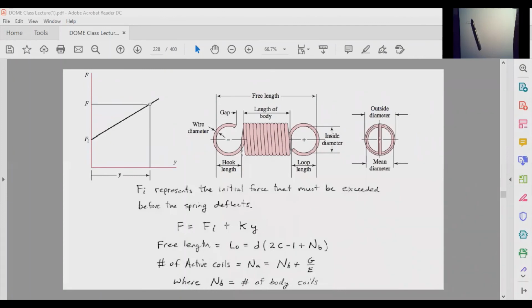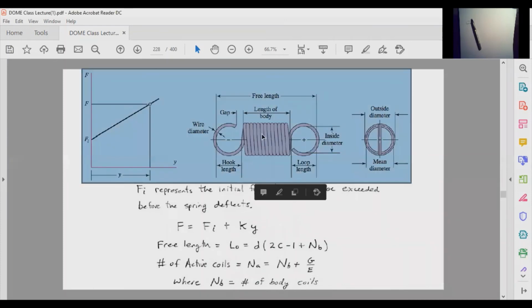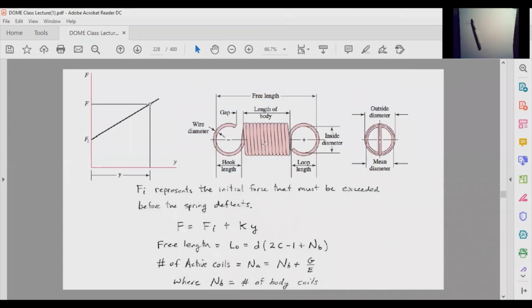In the case of the overall tension spring, we know the extension spring will always be in preload. If you pull on it and then let go, the spring will always come back to its initial orientation. As you create deflection, you have to apply a force that is greater than the preload in that extension spring.